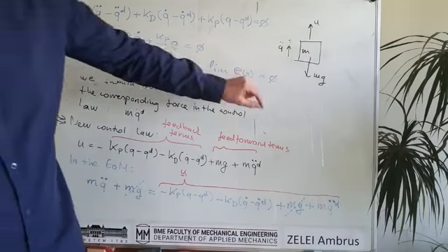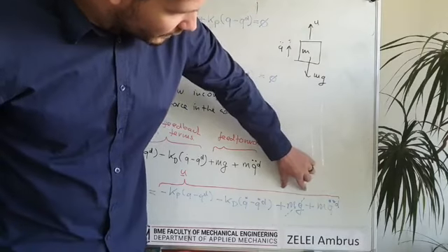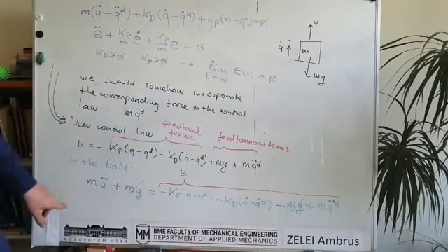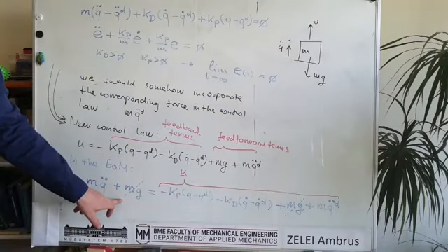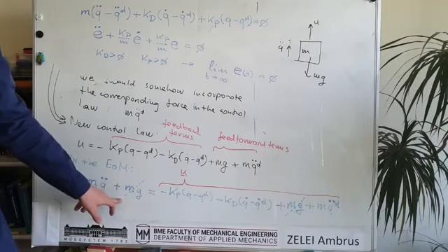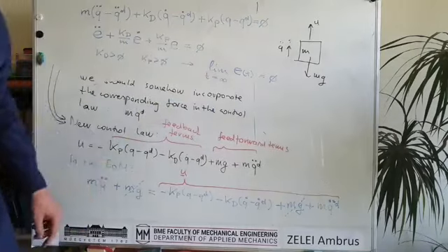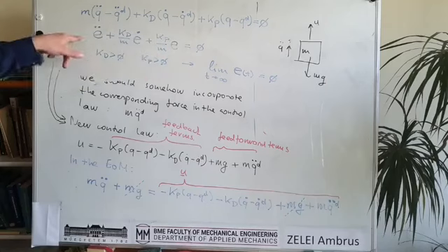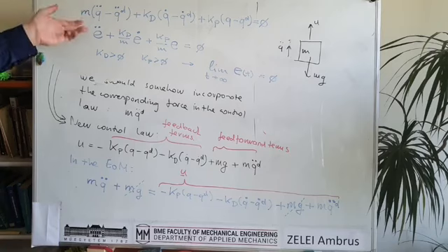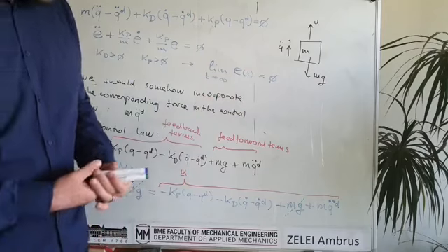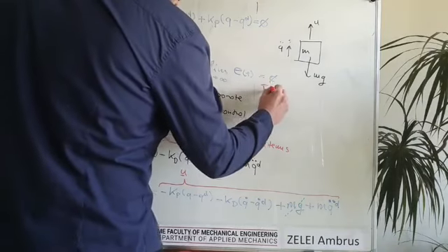But if you just feed forward some other terms like gravity and the desired acceleration, then you can cancel out from the equation of motion the terms which disturb us. So finally, by adding these extra terms, which are called feed-forward terms, you can guarantee that the positioning of your control will be totally accurate, so the control error will go to 0. So the tracking error will finally be 0.